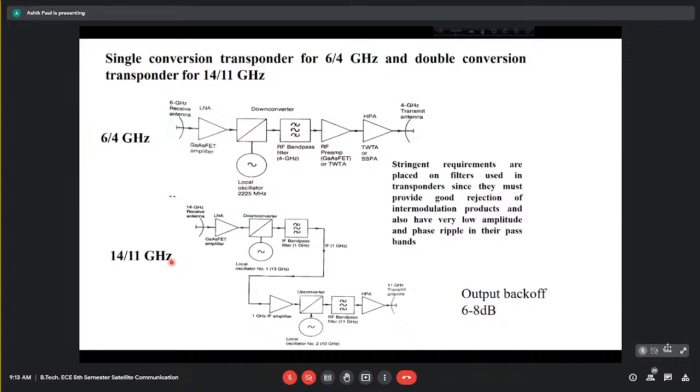or the upper atmosphere which is ionized, the levels of disturbances on the satellite signals are different, the ionized layer being much more dominant in causing disturbances at frequencies even up to say 2 gigahertz, starting from high frequency, which is around maybe 50 megahertz or so, going up to 2 gigahertz. Over this entire range of frequency, the ionized part of the atmosphere plays a very important role in causing disturbances to the satellite signals or radio signals.